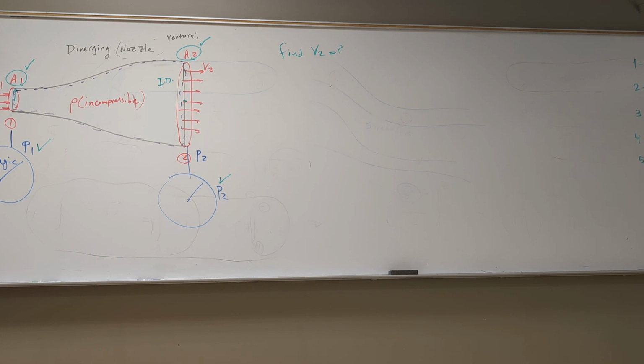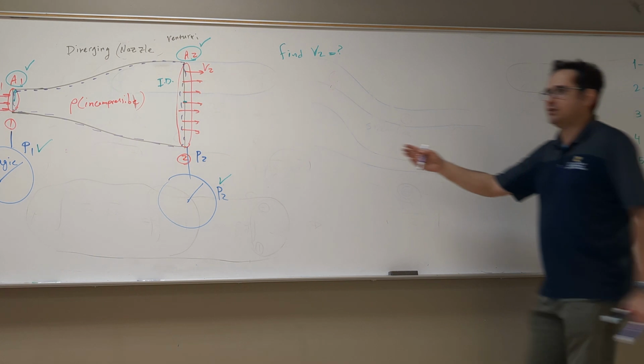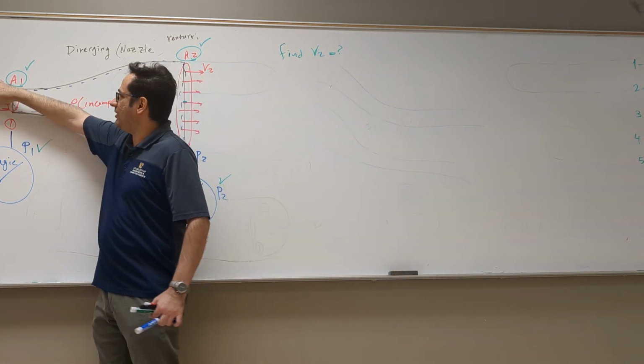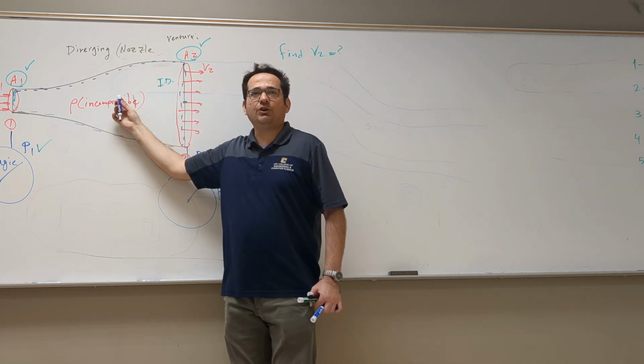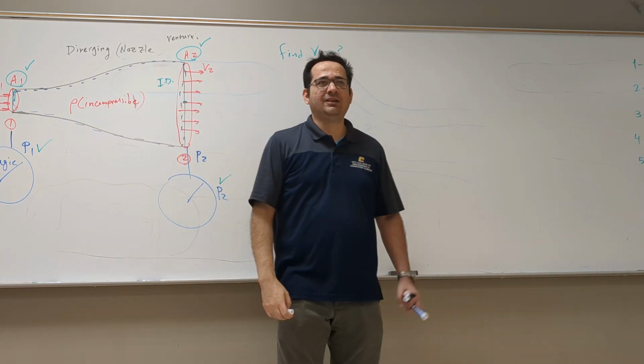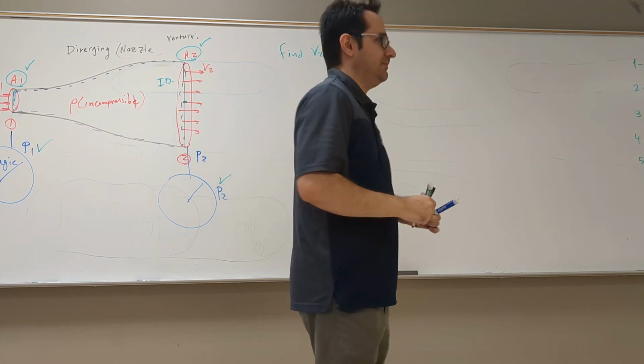4. You see that? So when you look at it, don't get tricked and say, well, this is only 2 equations. No, they will expand depending on dimension. Now, in this case, what type of dimensions do I have? They call this 1 dimension. Velocity doesn't have a v vector component, only u. So how many equations do I have? It's just 1 dimension. 2. 1 continuity, 1 momentum.